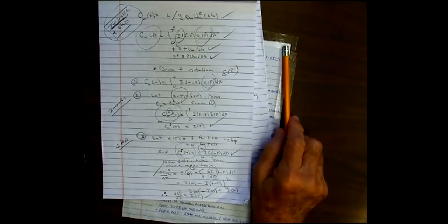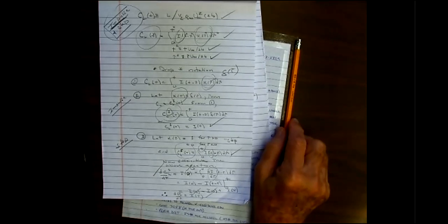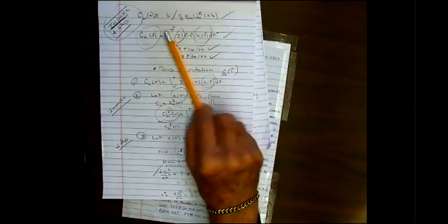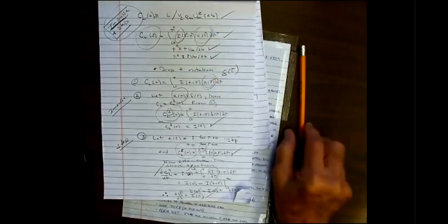Okay? Do you follow all that? I hope so. Yes. Okay. So what that means is if you have a linear theory or you have small motions, even if you're running a CFD code, don't keep running the CFD code every time you change the motion of the airfoil. Find the answer due to a step, and then use this formula for that moment. Because this is fractions of a second to compute once you understand the theory, versus running the CFD code, which makes for a much longer day.